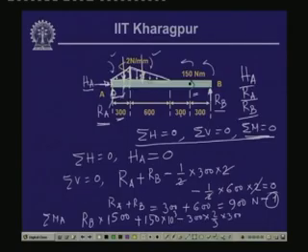The contribution of this particular loading: the loading is half of 600 times 2. So, this is again 600. Again this is in a clockwise direction, so minus. So, 600 into the distance. The action of this load is 1/3 from this end. Now, from here to here this is 600. So, this particular distance is 200 and the distance from here is 300.